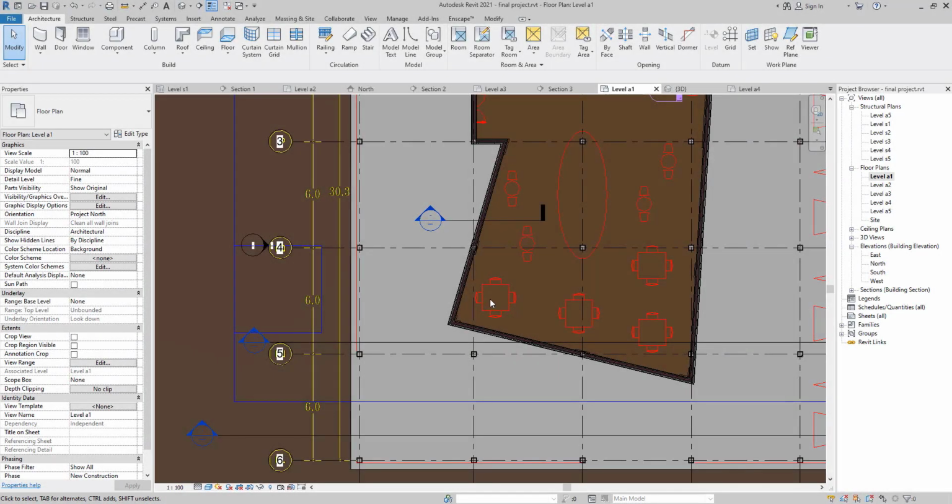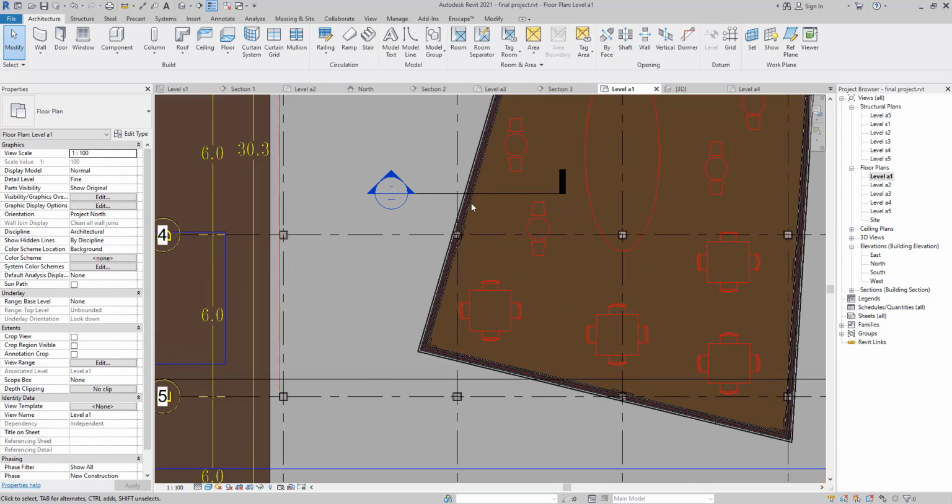In this video, we are going to draft our curtain wall. We need to consider one important point: I see people usually draft their curtain wall like this. For example, they have several levels, with floors and columns, and the wall covers different floors. Some people use the curtain wall system from the first floor to, for example, the fifth floor, and they draft this curtain wall as one element.